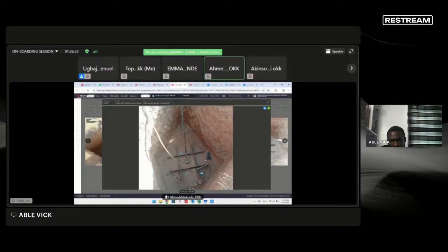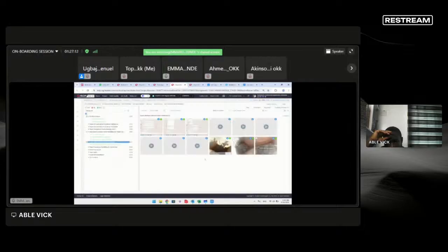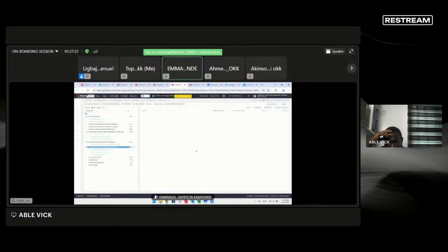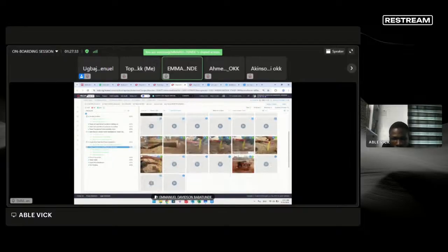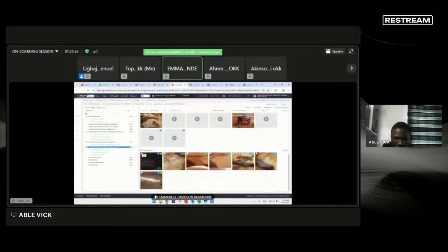But what we're explaining is the base plate installation. So you can label these base plates A, B, C, because you have three, for you to know you took different photos for your base plate. Then after that has been confirmed, you can commence your guide wire backfilling also. The same way you are backfilling your tower, you can backfill your guide wire trench. And for guide wire backfilling, because the compacting machine cannot enter at 2-meter depth, you can use manual compaction for that part, till you get to a level where you can insert your compacting machine to work on.